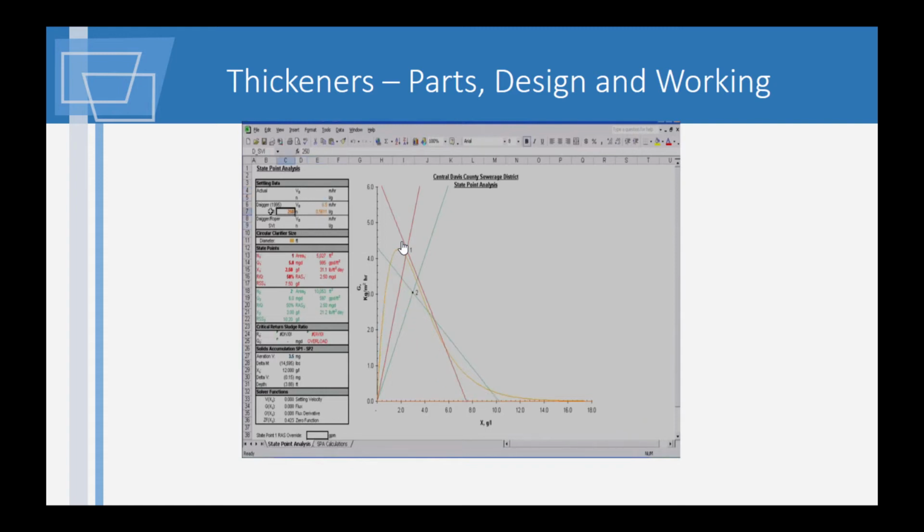The diagram model allows you to construct an approximate settling curve based on the SVI. We're going to assume that we have some decent settling sludge here, coming in with an SVI of 250. Let's make the clarifier diameter 80 feet and specify that only one is in service.